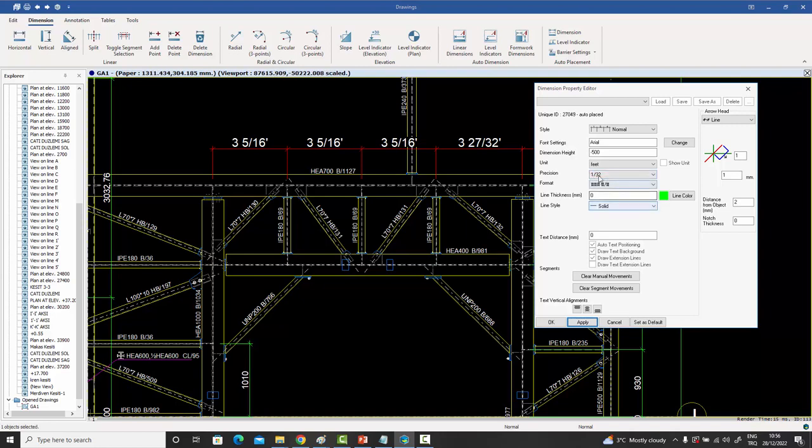So using these three new ones, if I were to change this feet one into inch and say apply, it will say it's 39 inches and 3/4 of an inch. This one is 39 3/4, this one is 39 3/4, and this one is 46 1/16th. Like I said before, despite the fact that I have chosen this 1/32 option, it will round it off downwardly if it's perfectly divisible by a smaller multiplier. So if I change this, for example, to 1/8, maybe it'll change that. Yeah, so it changes this one in that case.